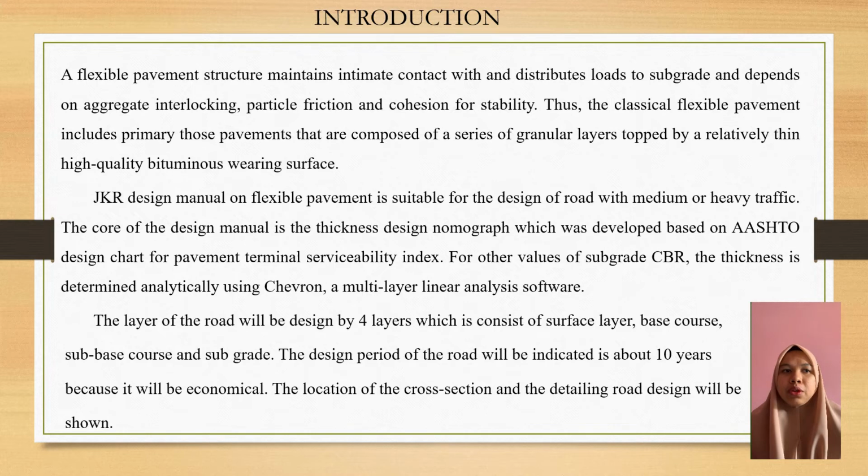The JKR design manual on flexible pavement is suitable for the design of roads with medium or heavy traffic. The core of the design manual is the thickness design nomograph, which was developed based on the H2 design chart for pavement terminal serviceability index. For other values of subgrade CBR, the thickness is determined analytically using Chevron, a multi-layer linear analysis software.